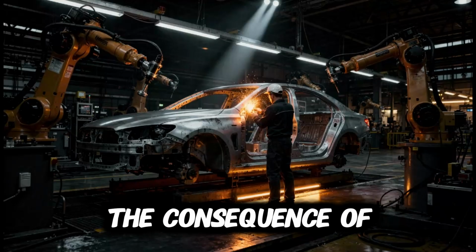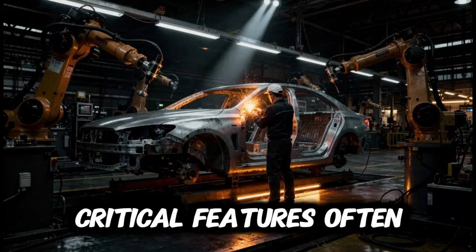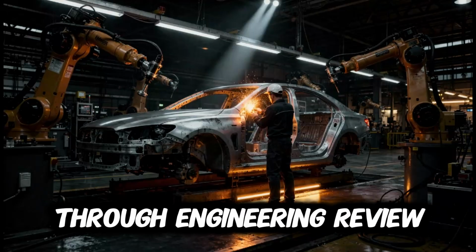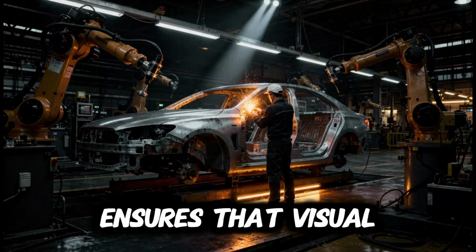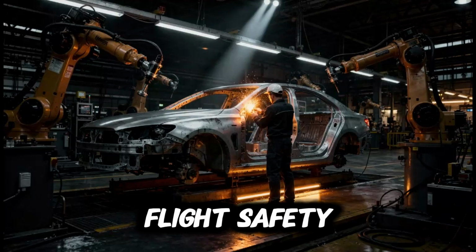The consequence of visual inspection failure in aerospace drives redundant verification steps. Critical features often require independent inspection by two qualified personnel, with disagreement resolution through engineering review boards. This layered approach ensures that visual testing, despite its apparent simplicity, meets the zero-defect expectations of flight safety.